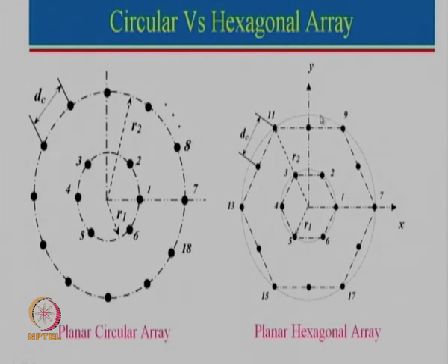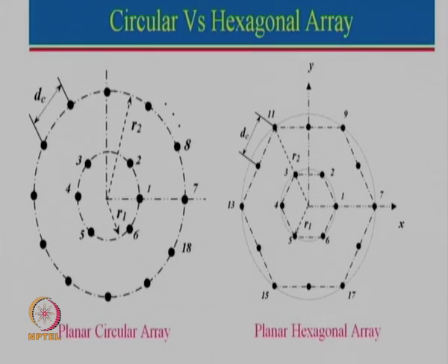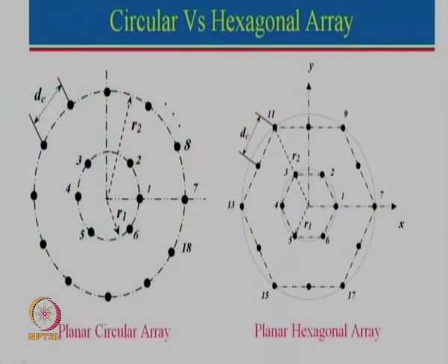So now there are 2 ways to do it. One is we need to find the array factor for this here. For a circular array, it is defined in terms of the Bessel function, so you can write this function in the form of a Bessel function. Those expressions are available in the textbooks which I had mentioned, Balanis and the Cross book. However, for the other elements which are missing over here, we can either use the Bessel function concept, or we can consider these elements separately and then add them together.